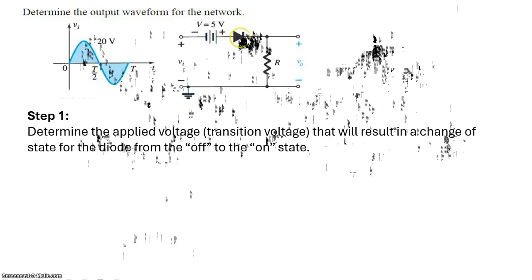But it is just going to be on only, so still there is no current. The diode is just at the point of opening, so the current IR, the current through the circuit, since only one current will flow, will be equal to 0. So at the moment it is going to be on, the current through the circuit will be equal to 0, as well as the voltage across the diode, Vd equal to 0, considering that the diode is ideal.